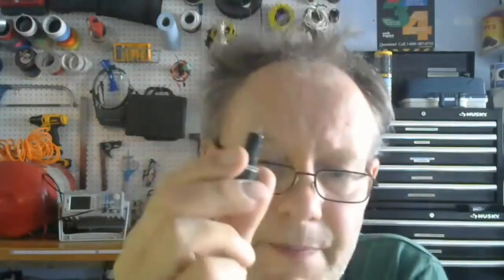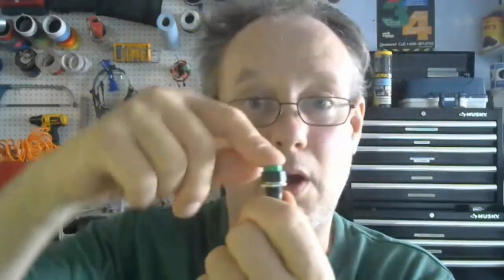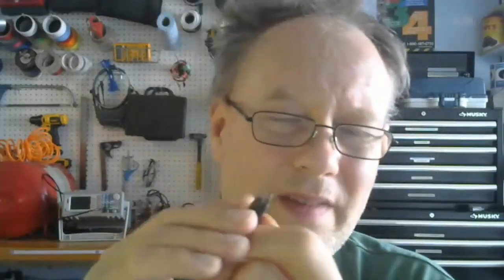But let's take a look at this guy. I have this little single pole, single throw, normally open push button, okay? These contacts are pretty small. I might put an amp through this, but I wouldn't want to put more than an amp through that. I wouldn't mess around with that. I don't know what the specifications for this are. I'm looking for a product code, and I can't see one. So I would just roll with not going over an amp.